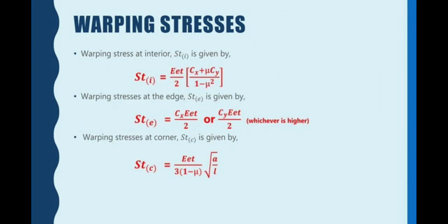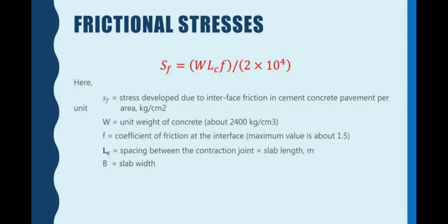Warping stresses at the interior, edge and the corner, the formulas are given. Frictional stresses are calculated using the formula SF is equal to W L Cf whole divided by 2 into 10 power 4.